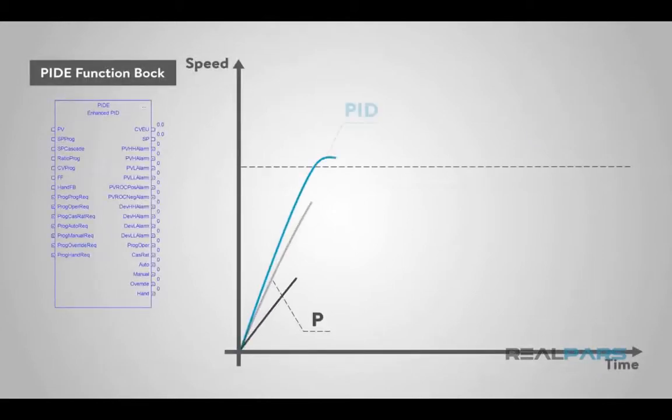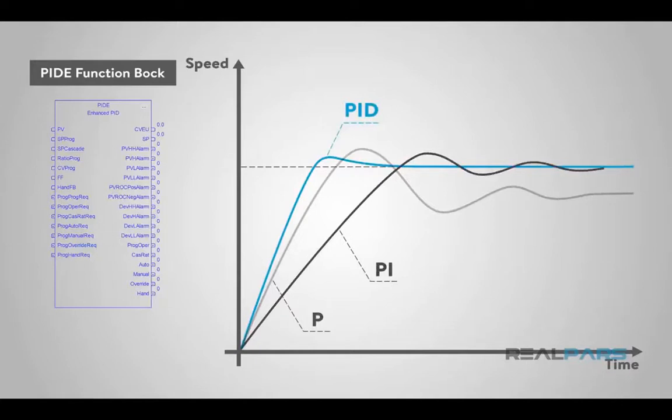If you enjoy function block programming, as I do, you will benefit from using this enhanced PIDE instruction over the standard PID instruction for a few reasons. The PIDE instruction offers a built-in auto-tune feature, which works reasonably well. The PIDE is programmed using a function block and is not available for ladder logic programming. It uses the velocity form of the PID algorithm.